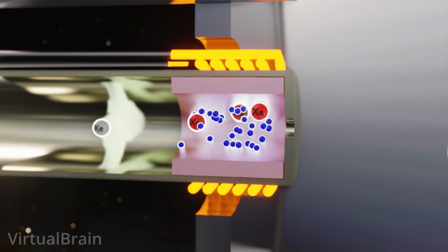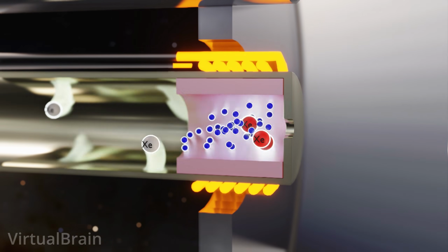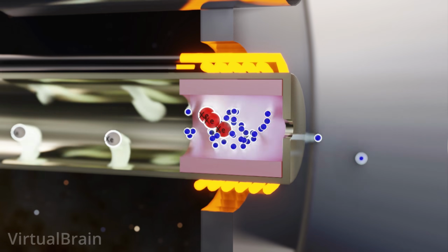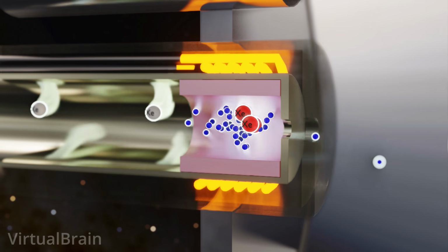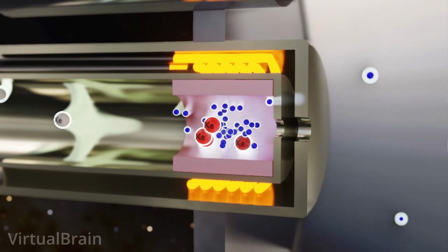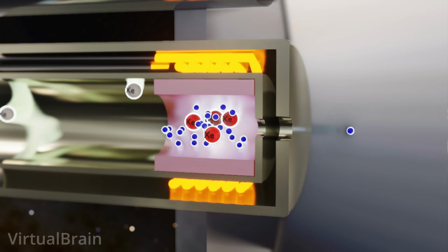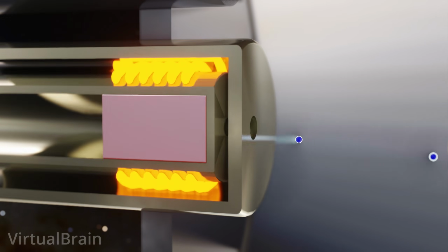Now we will have a plasma volume composed mostly of electrons, and since xenon continues to be injected from the rear, it will be forced out through the hole. Furthermore, to aid this process, a positively charged cover is added, which has a dual function. Firstly, it guides the electrons into the orifice, and secondly, it prevents other particles from entering the section where the plasma is generated and affecting its operation.